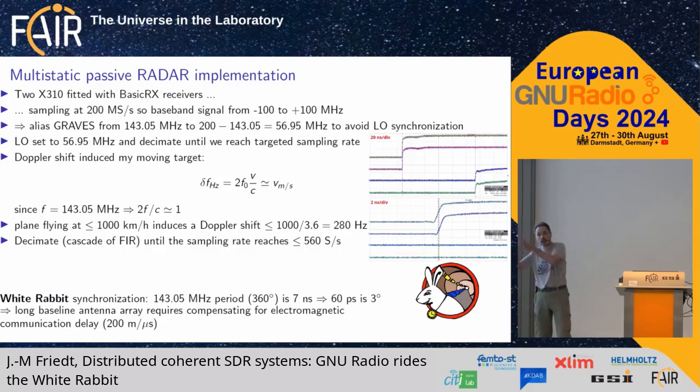So you're sampling a megahertz signal, and then you need to decimate until you reach a few kilosamples per second. And one nice thing with White Rabbit is that it's a gigabit Ethernet switch, meaning that you can also broadcast the data over the fibers of White Rabbit. I don't need to go through all the firewalls that you've seen. I would have to go through the Besançon Observatory, I would have to go to the university.